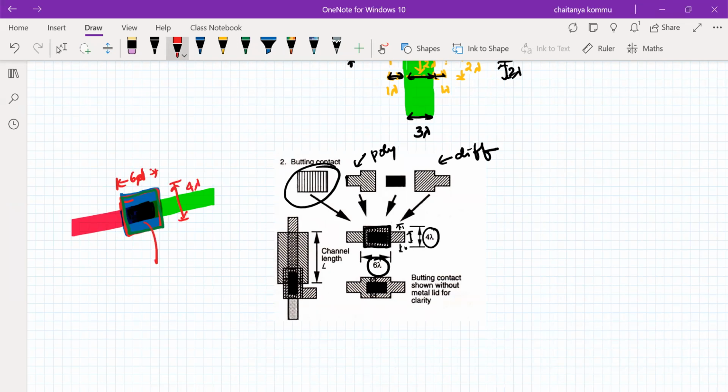So now what is the contact size then? Any guess? Here 1 lambda, and 1 lambda over there. That means 2 lambda is the one thing. And what is the distance between these two? It's 6 lambda, which means we have to maintain 1 lambda here and 1 lambda here. So out of 6, 2 lambdas for both sides and the 4 lambdas. 4 lambda by 2 lambda is the contact size. It's the contact cut size. We have to maintain it in this way.